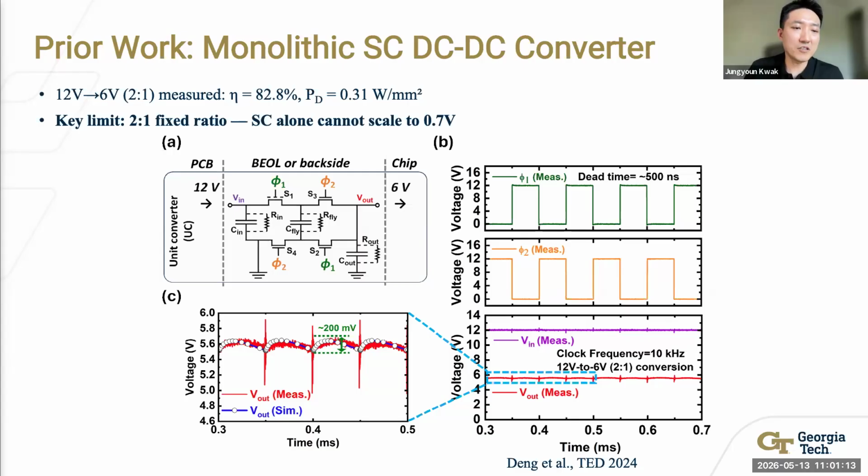Yes. First, the reliability. Thanks for the question. The transistor reliability itself is not there yet. If you imagine a silicon tape-out, it's not as good as silicon transistors yet. I think amorphous oxide transistors have their own weaknesses. It's a short time to go over all the details, but in the channel, if you have some byproduct, let's say hydrogen, it can modulate the threshold voltage by a lot.